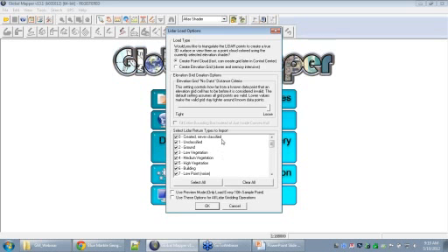And as well, at the bottom, we have all these different types of classifications of the point returns in the LiDAR file. For those of you maybe new to LiDAR, each individual point has what's called a classification, and it tells you what that particular point is. So you'll see there's a number of different things we can identify in there, things such as the ground layer. That's what we would use to create, say, a bare earth surface model. We have areas of vegetation, low, medium, and high. So that's going to cover stuff from low scrubby bushes to tall trees, buildings, and a number of other pieces, as well as some open fields down at the bottom that were sort of left open in the specification for various other purposes.